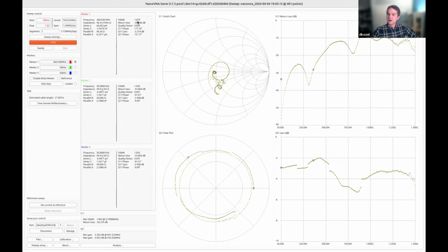We can see our SWR, 1.07. I think most people would be pretty happy with that. But as we get up to, again, that negative 20 dB point, we're getting to an SWR of 1.2. We're still mostly transmitting, or mostly propagating, our power forwards. But that's our attenuator. I'll throw the filter in so that we can take a look at that.